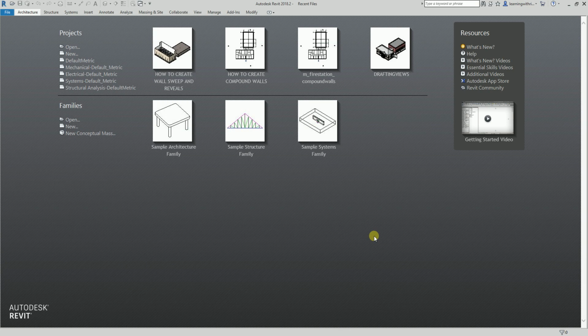This is the continuation of our discussion for the Revit Architecture Certified Professional Examination Review. For today's topic, we're going to talk about how to create family parameters. You can create new instance parameters or type parameters for any family type. The reason we create new parameters is so you have more control over the information contained in each family instance or type.